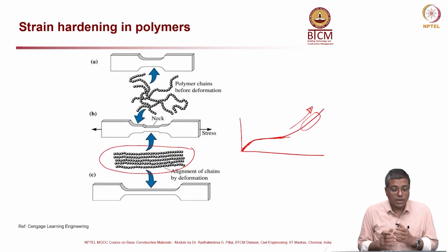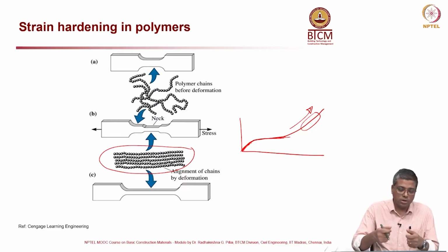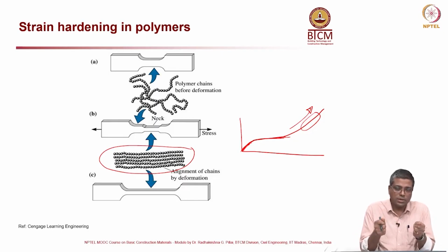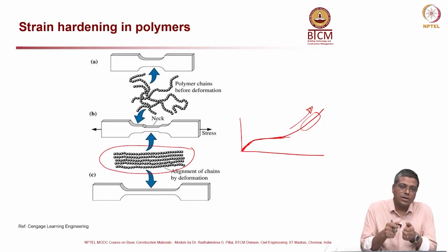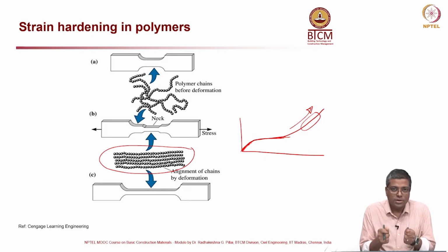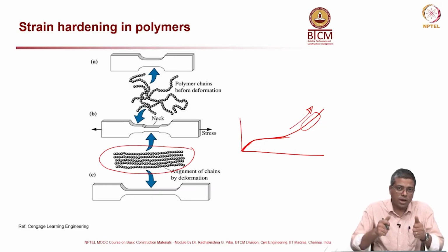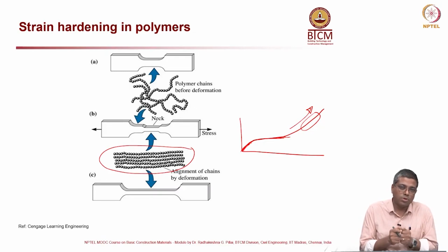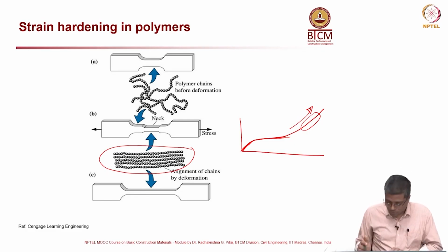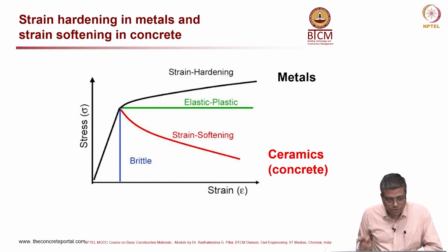One example of this is the polythene bags which you use in shops. You try to pull the plastic handle of the plastic bag. Initially it will be very easy to increase the length of the plastic, but after some time it becomes very difficult. That is because initially when you pull it, the polymer chains try to get straight, and after some time they are already straight. So, now they start taking the load, so it becomes stronger. Hope it is clear.